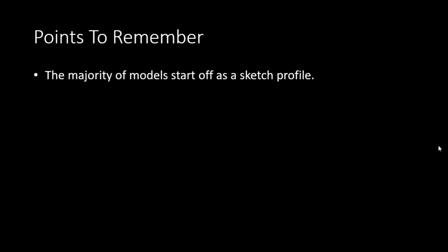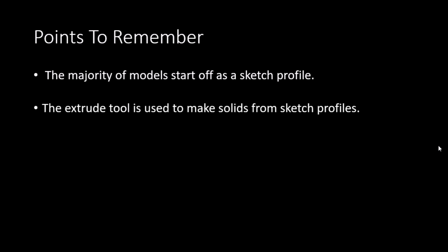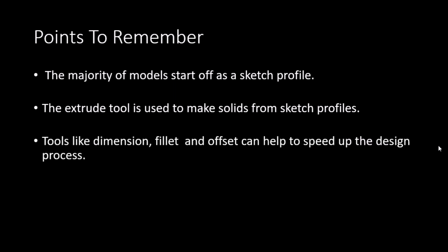Here's some points to remember. First of all, the majority of models start life as a sketch profile, so please make sure that you're using sketches to help you create your shapes. Secondly, the extrude tool. It's not the only way of making solids from sketches, but it is one of the most common, so please learn it and practice it as much as you can. And then finally, tools like the dimension, the fillet and the offset tool are really good at speeding up your designing, so please get used to using them.